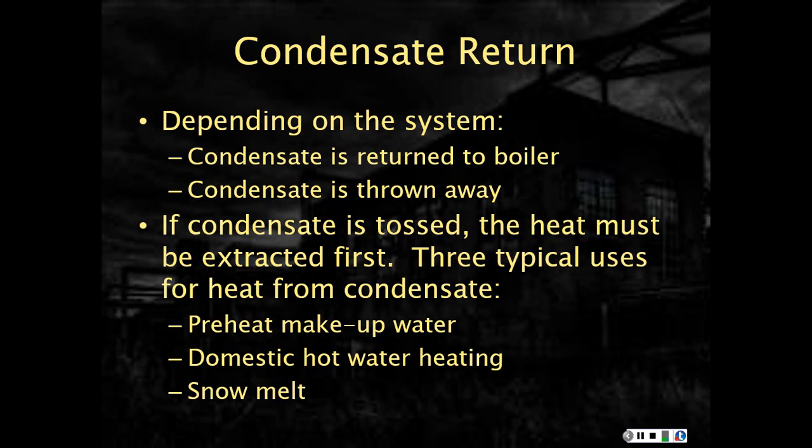Now again, most jurisdictions or by code do not allow hot condensate simply to pitch to the environment because of the adverse effect of that overly hot water to the environment. So here in Michigan, you have to drop the hot condensate below a certain temperature before they allow you to discharge it, and this is the reason that this hot condensate is run through these different mechanisms to dissipate heat.